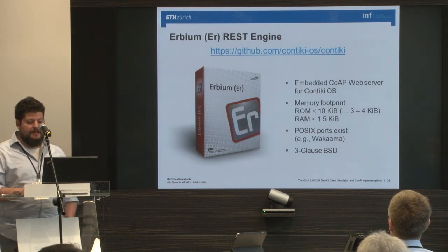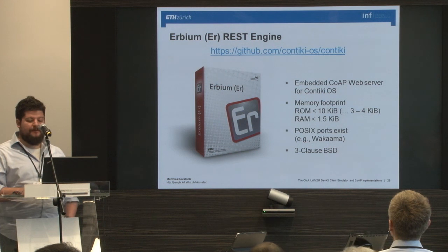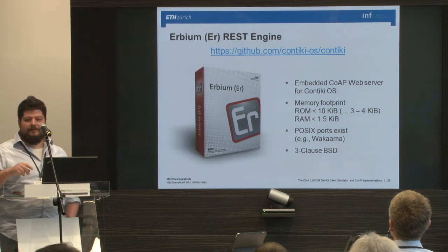Another project by me is the Erbium REST engine. That's the default CoAP implementation in Contiki, so it's part of the Contiki operating system. The focus here was actually to have a CoAP web server running on Contiki. It's similar to the concept you have in lightweight M2M. The main thing is that you provide a server that hosts resources, so you can read out sensor values or write some parameters there, control actuators.